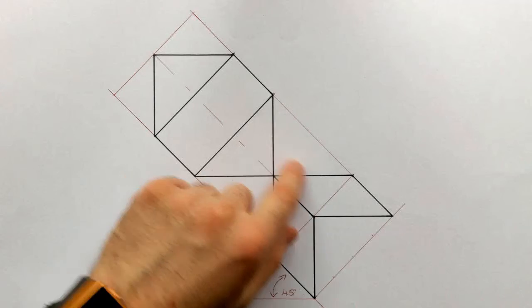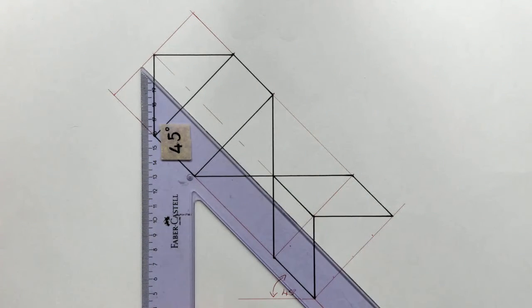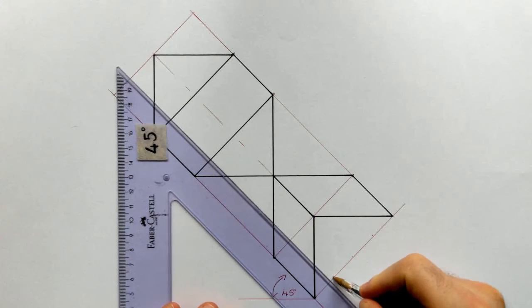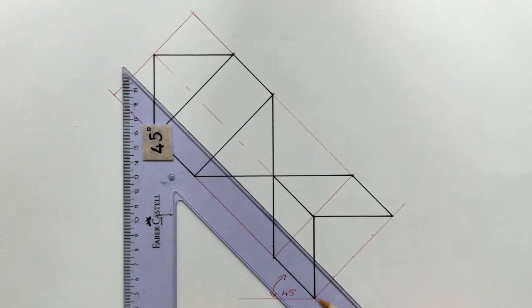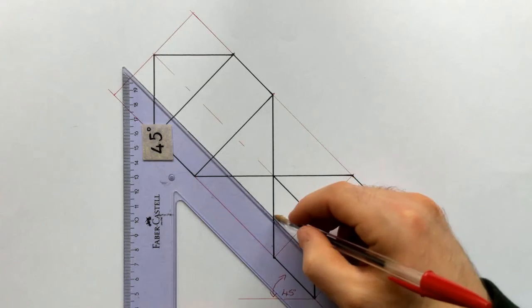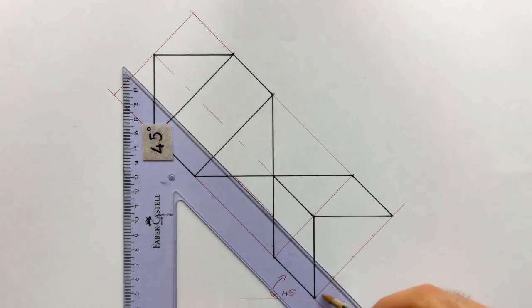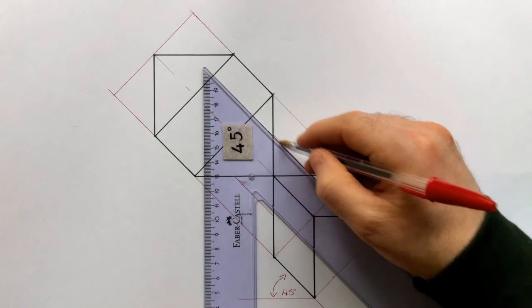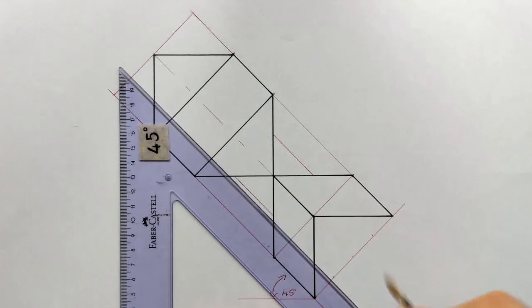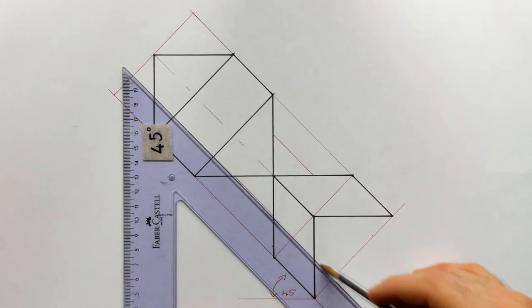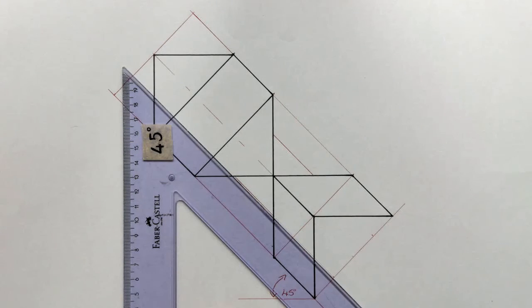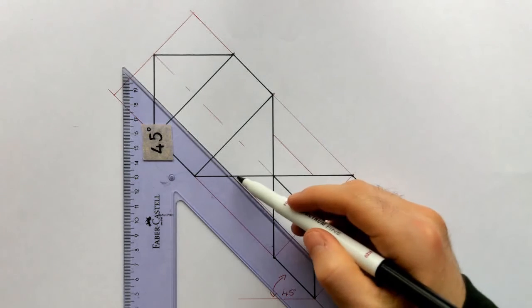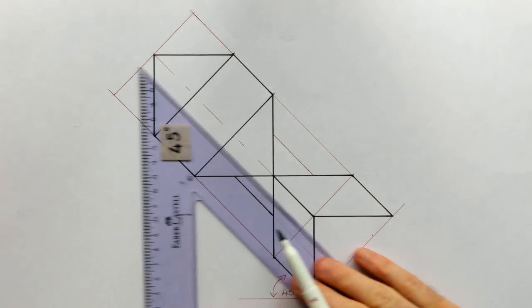We have these little edge pieces here, which are marked up from the 20 millimeters that we measured previously. So I can mark them up there. So that 20 that I marked down here. Okay, I'm just going to mark it inside here to keep my drawing neat and tidy. If you wanted, you technically could do a construction line the whole way. I'm just keeping my drawing neat and tidy. And then finally, just heavy in the detail.